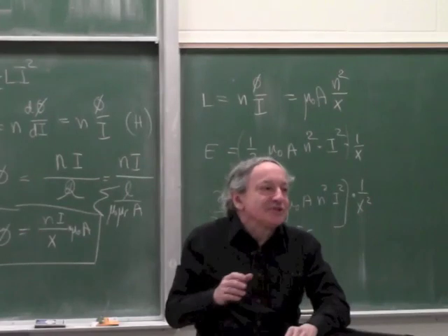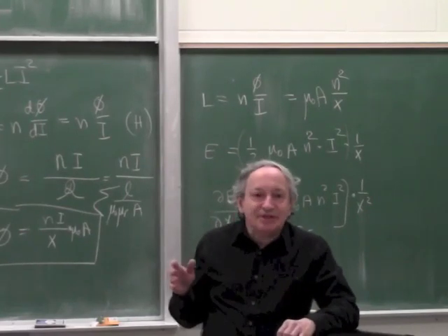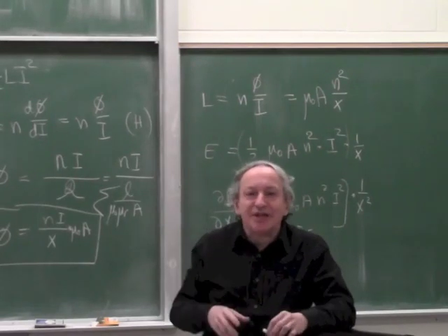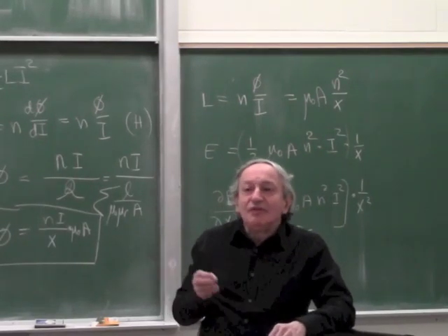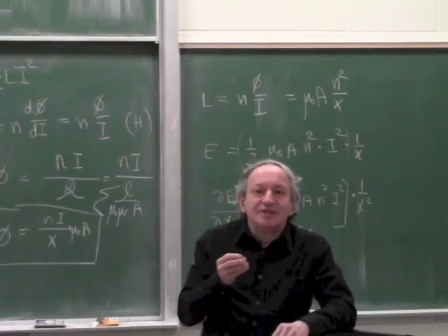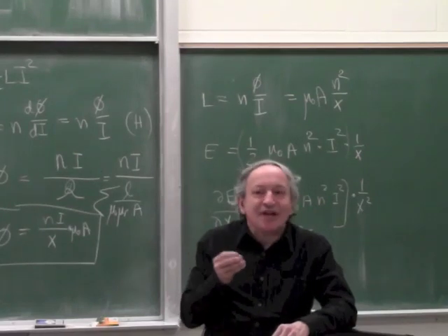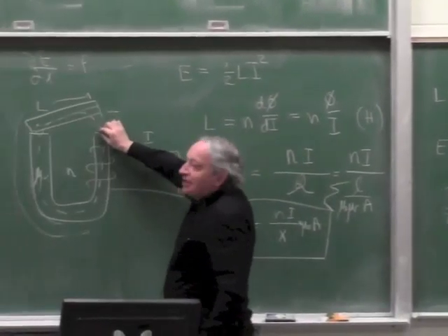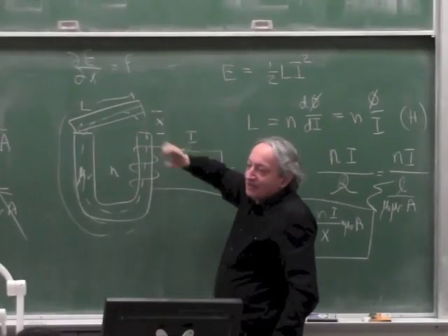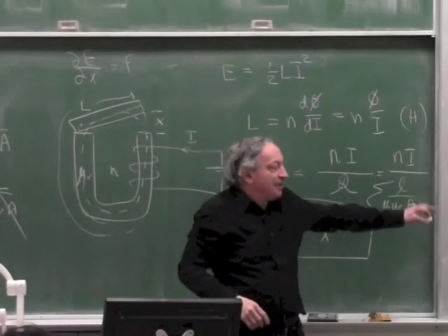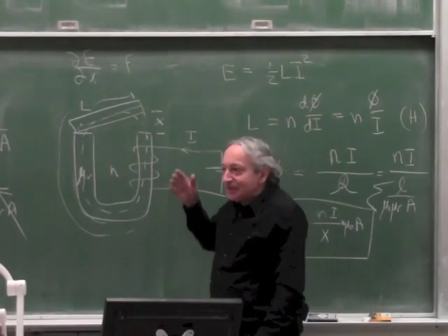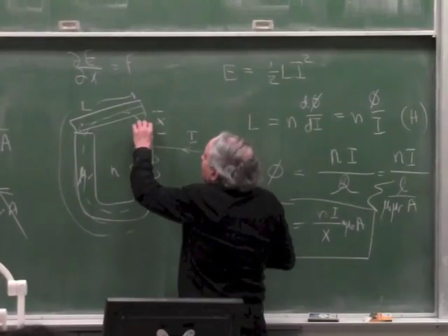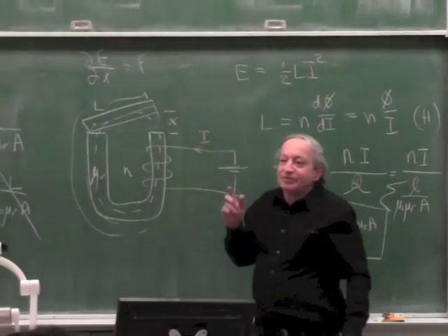The limit of all servo systems is stability. We harped on it long enough, right? The stability of phase shift, you have too much gain, it oscillates. If you have variable gain, you have to design your servo system for the highest gain. When this comes near closure, the gain becomes infinite actually, right? According to at least the approximation we have. But let's say it's not infinite, you control the gap, so you only allow the gap to go to here, but the gain becomes very high.